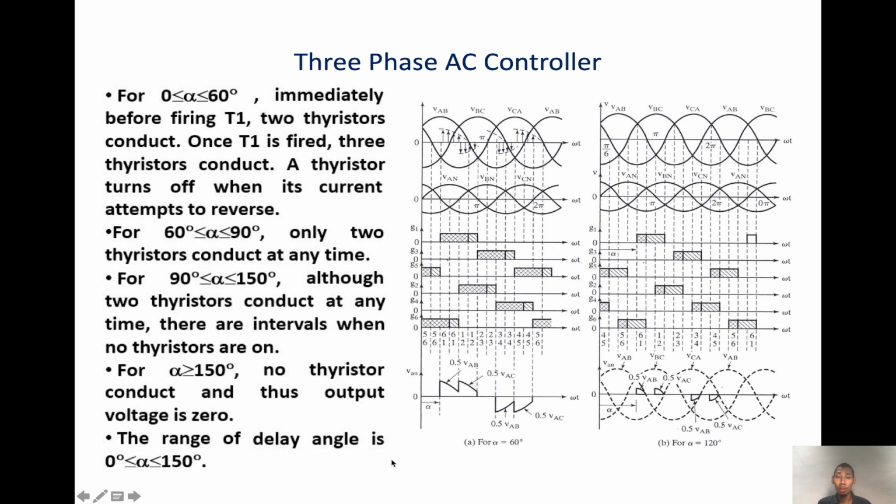So when you want to plot it, this information is very valuable, to know which sequence of thyristors turns on, to allow you to know whether you are plotting the phase voltage or half of the line to line voltage.